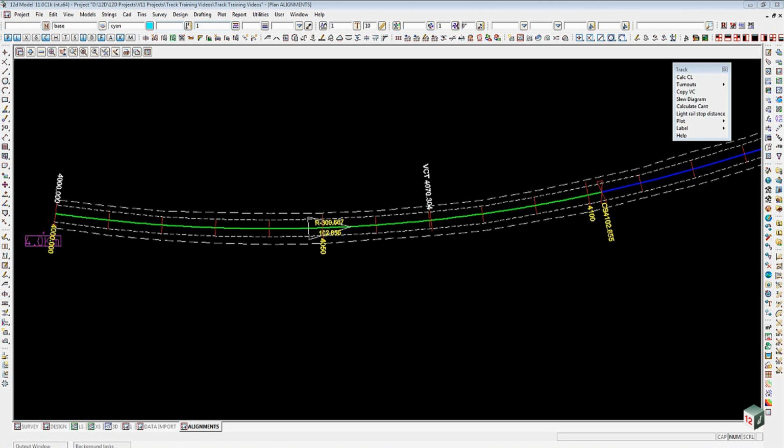of track. It's important to understand that the chainage equalities give you, if you like, a second tier of chainages along the string. In other words, you will always have the raw or real chainage of the string embedded in the string, and all that we're doing by putting chainage equations or equalities onto that string is to fool the display into showing us different chainages along that string. This of course then means that we will have to use a couple of tools later on to see exactly which one is the raw chainage and which one is the equality chainage.